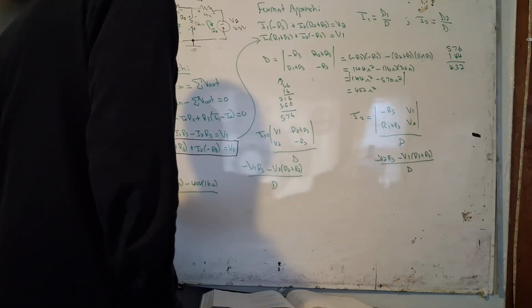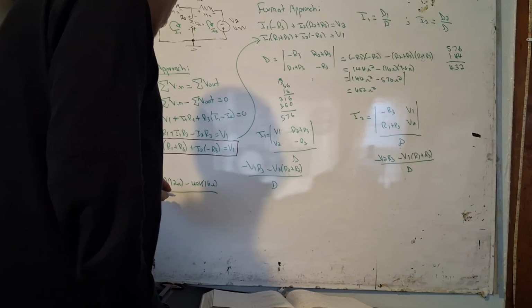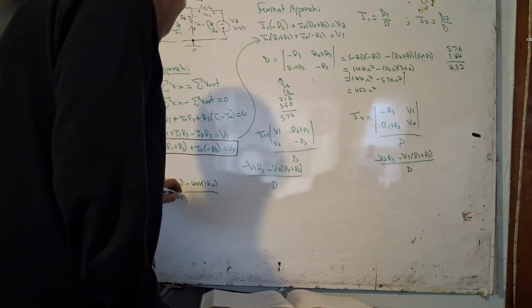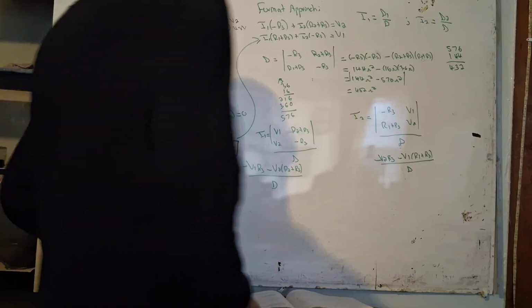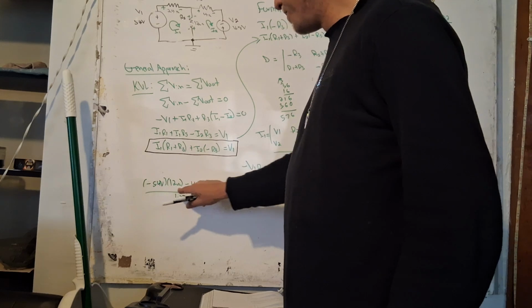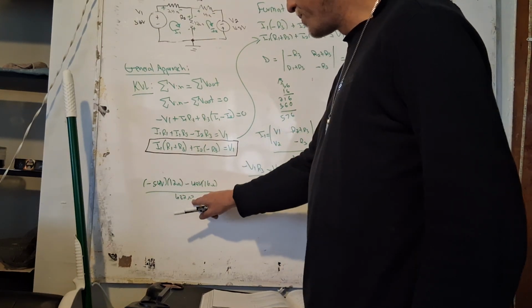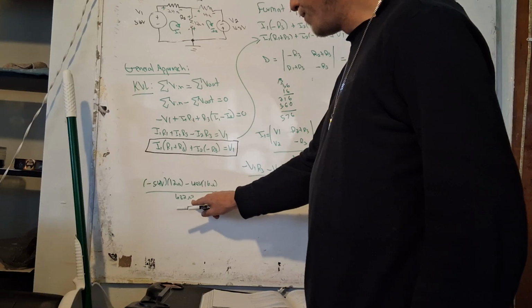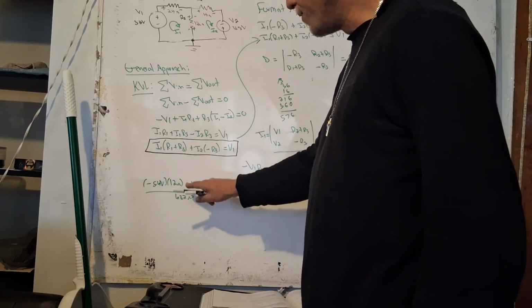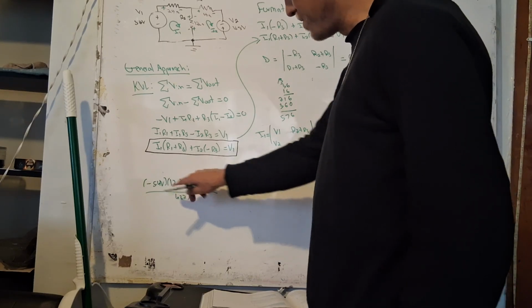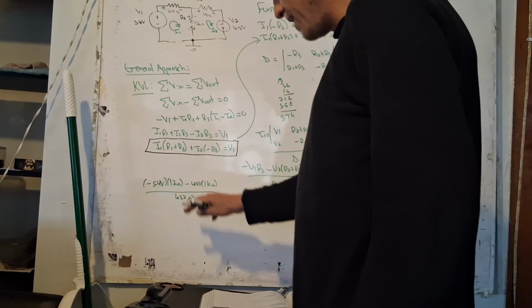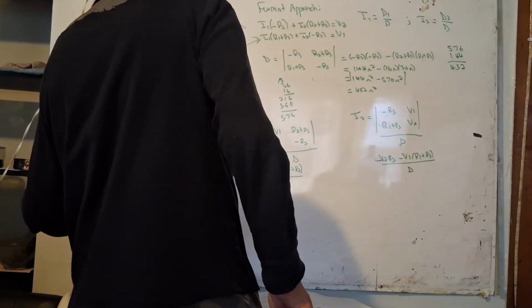And we're going to divide that by 432 ohms squared. Notice that volts and ohms is going to be added to volts and ohms. And then the volts and ohms divided by ohms squared leaves you with volts divided by ohms, which is equal to amps. So this whole expression leaves you with an amperage. This is I1.